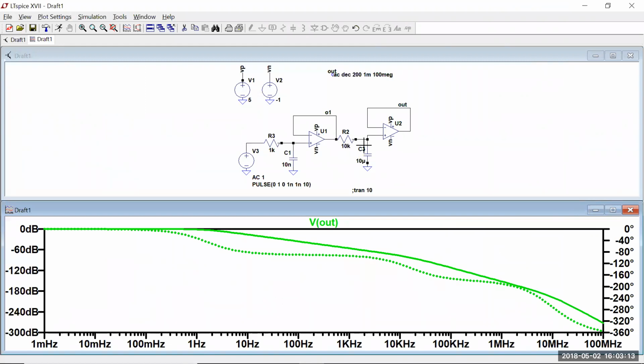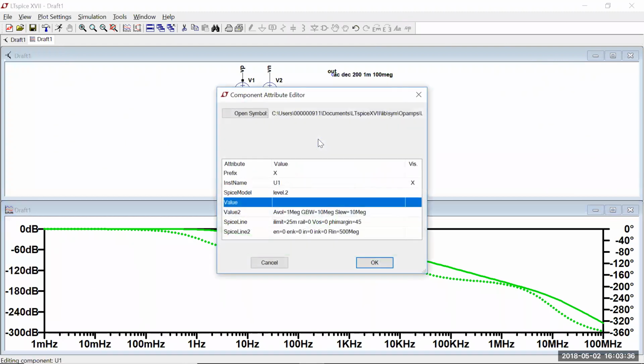Right. They have capacitors. So the reason this is going on is those op amps have capacitors that have feedback on the inside to prevent things like ringing, and so they are adding that.